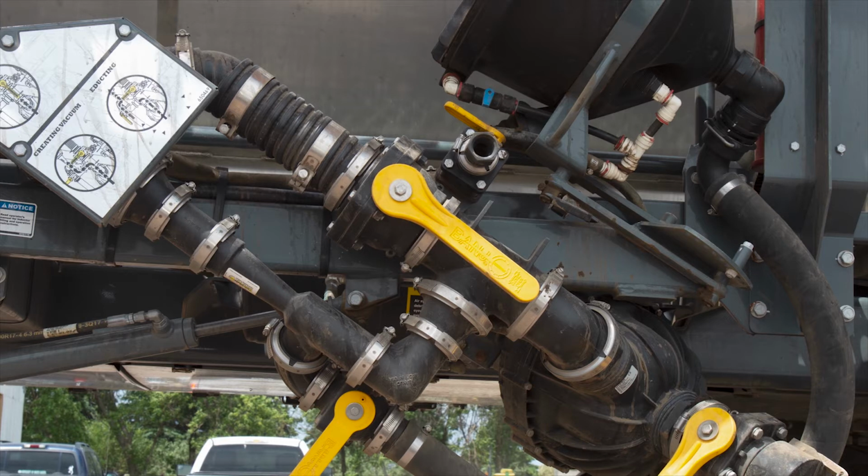When we look at the side of our Hagie machines, we have the option for a couple different fill options. We've got front fill, rear fill, and a side fill option. When a machine has a side fill option, it includes an eductor. What differentiates this Hagie machine from most other machines in the market is there's actually a Hypro pump on the side here. So if we load with the machine, not with the nurse tank, this Hypro pump will actually operate and load our product in.